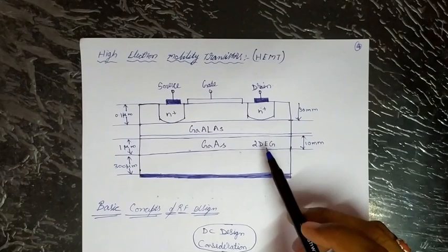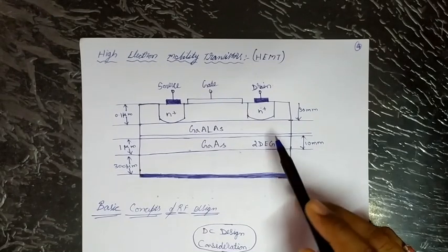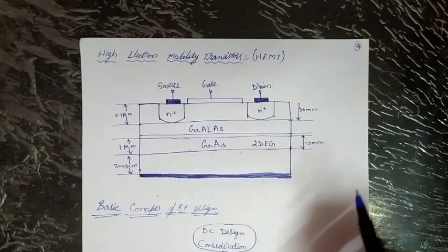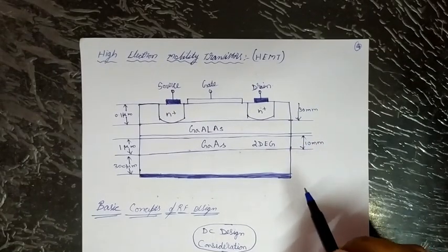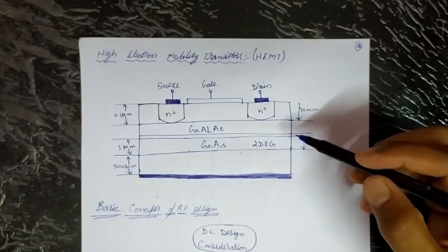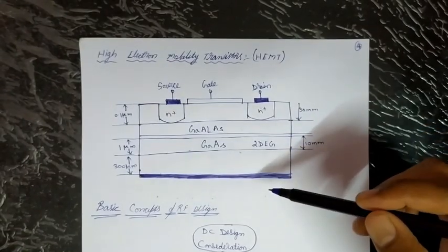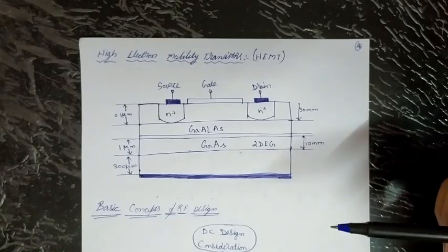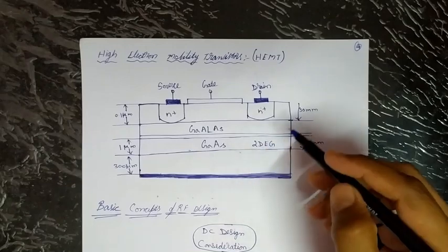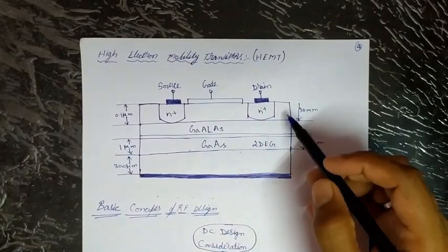The two-dimensional electron gas forms an n-doped layer in GaAs at zero gate bias because the Fermi level is above the conduction band. So the electrons accumulate in this narrow potential well. The electron concentration can be depleted by applying increasingly negative voltages to the gate.